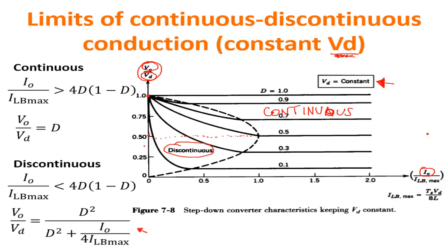So if you consider for a minute the complete DC-DC switch converter, let's think about what you need. You need one switch, one diode, one capacitor, one inductor, and you need typically a finite state machine or a microcontroller in order to perform the regulation.